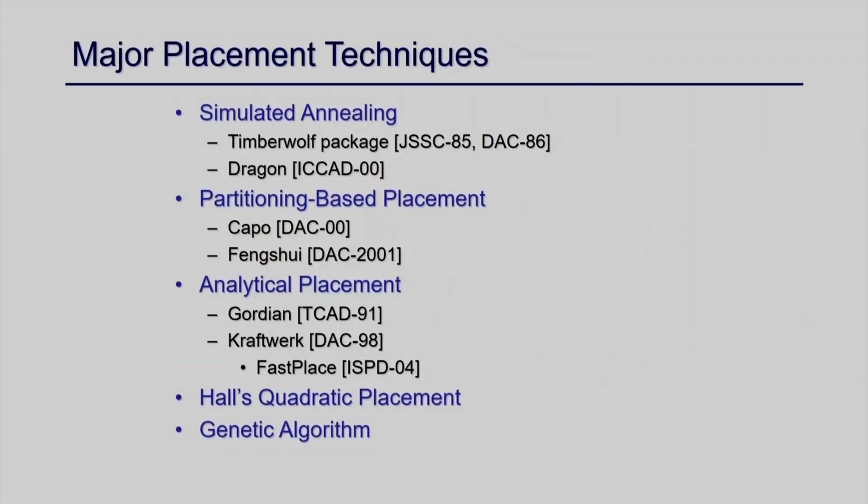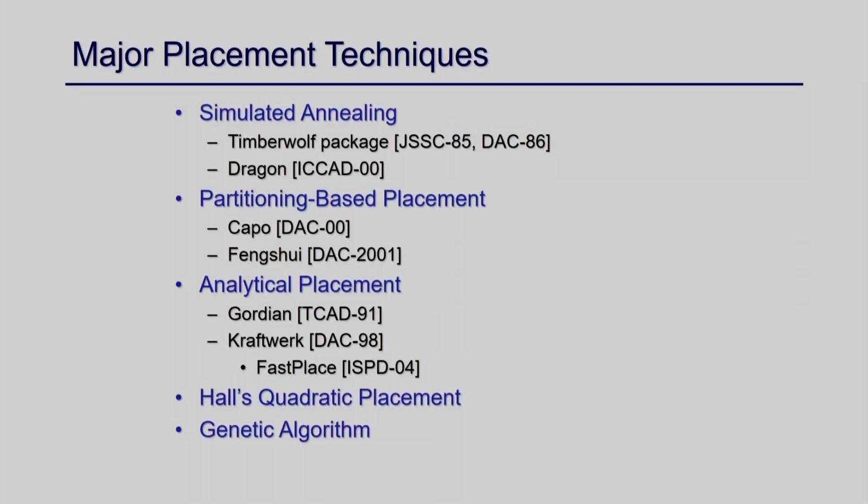Okay. Again, placement is also an NP-complete problem, and you have various approaches like simulated annealing, partition-based approach, analytical approach, and so on. Again, I am not going to discuss all of them in detail, but the basic objective is understood here: to reorganize your placement, repositioning your blocks so that you can reduce your total area and primarily total wire length.